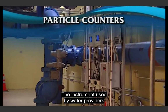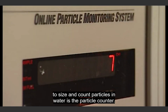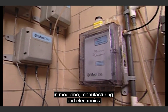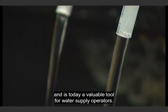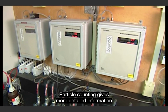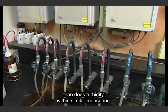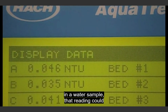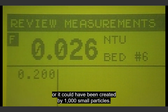The instrument used by water providers to size and count particles in water is the particle counter. Particle counting has been long used in medicine, manufacturing, and electronics, and is today a valuable tool for water supply operators. Particle counting gives more detailed information than does turbidity, with similar measuring. For example, if you have a reading of one turbidity unit in a water sample, that reading could have been created by one large particle, or it could have been created by 1,000 small particles.